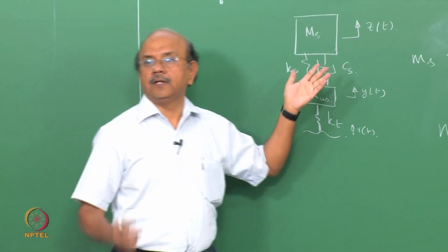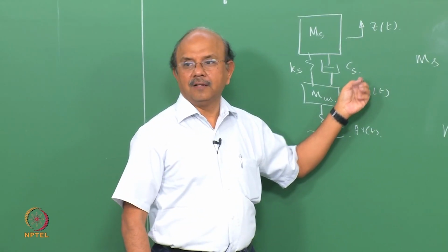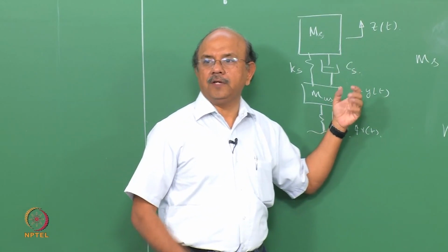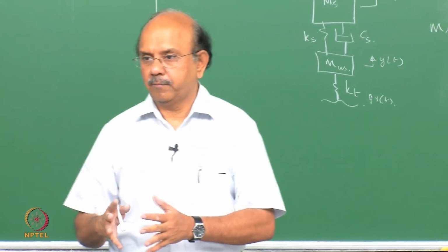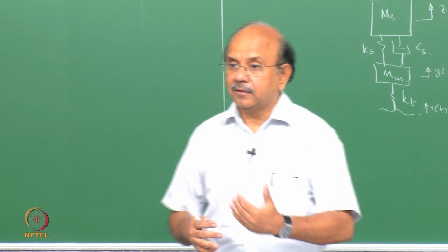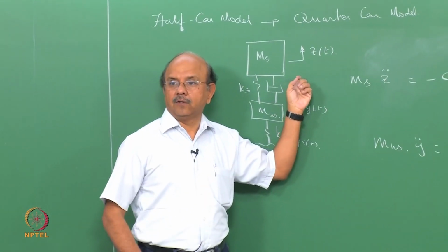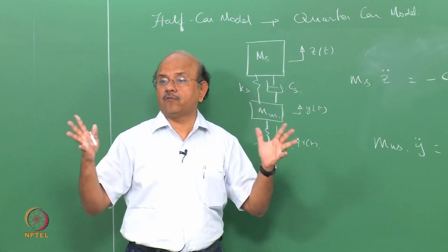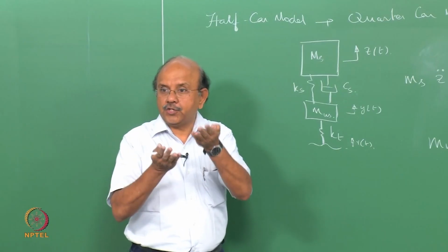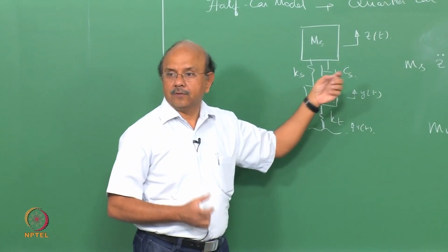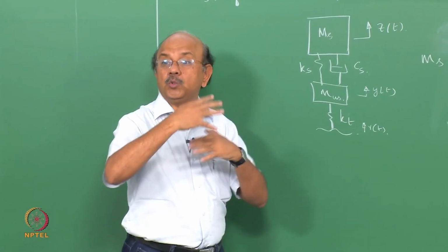For example, in a typical car, if I don't have a damper, the ratio of motion will be 80 times, say, for omega 2. But if I put a damper, then the ratio of motion comes down to nearly 10. In other words, there's nearly an order of magnitude difference in the ratio of Z by Y, the ratio of displacement or motion.